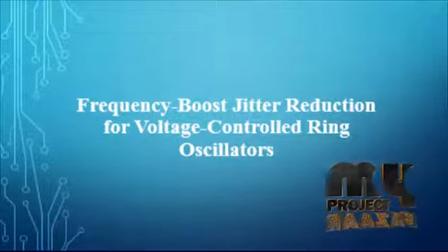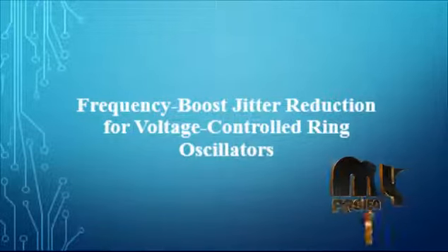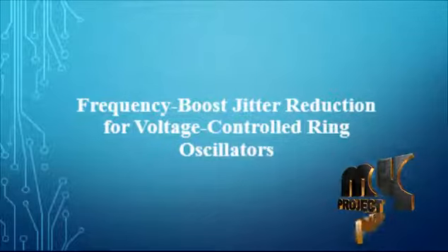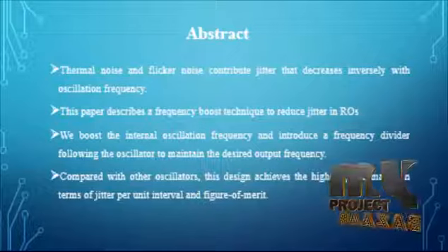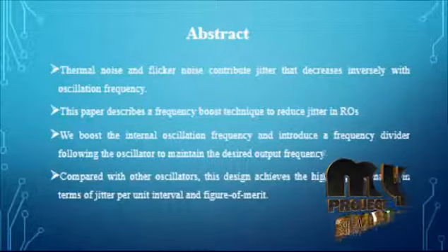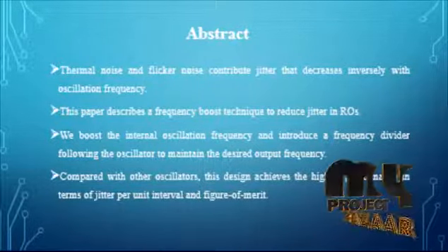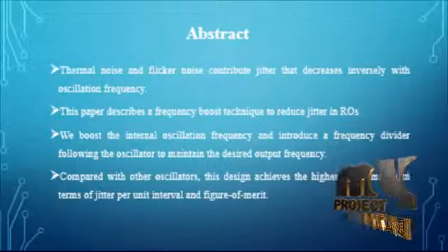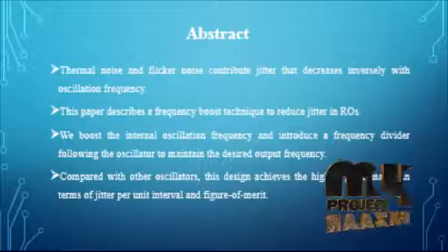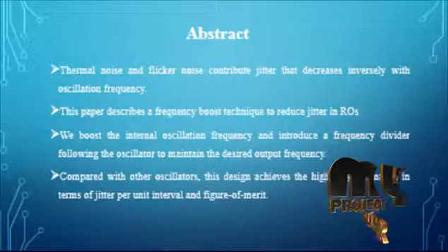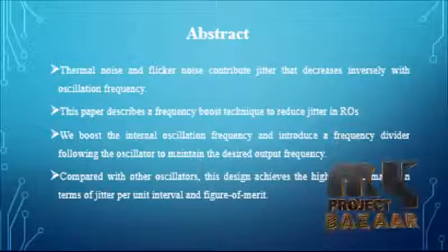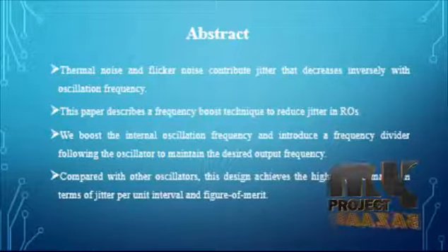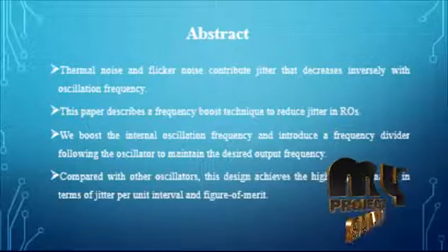The title of our product is Frequency Boost Jitter Reduction for Voltage Controlled Ring Oscillators. The abstract of our product is: ring oscillators are popular due to their small area, modest power, wide tuning range, and ease of scaling with process technology. However, their use in many applications is limited due to poor phase noise and jitter performance.